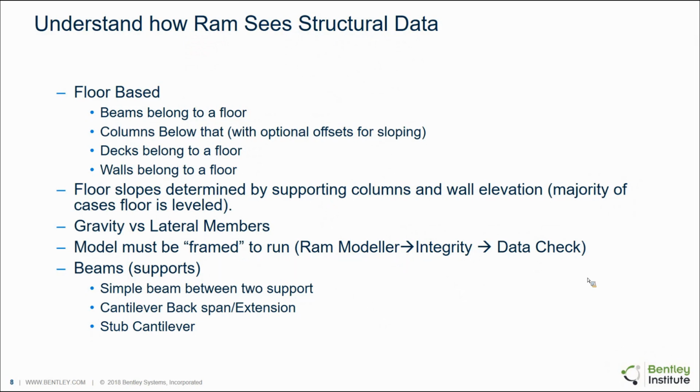There's also a difference between gravity and lateral members, depending on whether you're analyzing them in Concrete or RAM Frame. And we can't just bring members in and be satisfied with that. At the end of the day, it's an analysis program, so it must be framed to run. So your RAM Modeler integrity data check must pass. That adds an extra layer of complexity.